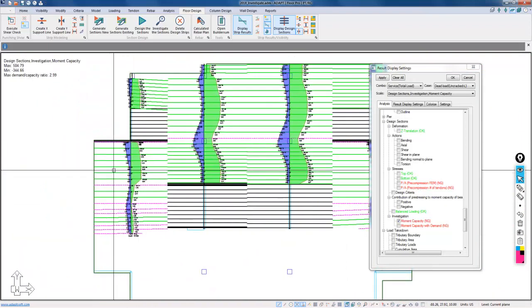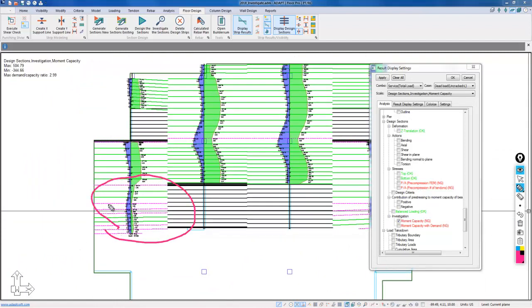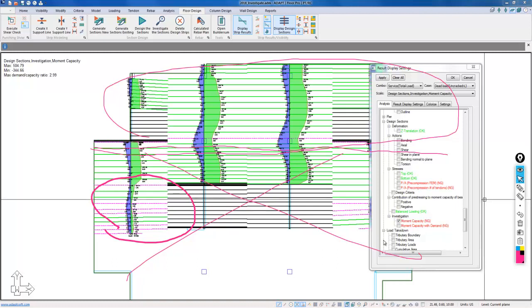Notice also that if you have a design cut, for example, we have actual design cuts back here, the program will check those design cuts also. So we may want to avoid what's happening back here, but if we put a support line back there, we're going to get results. So in our case, we're really only concerned about what's happening up here, so we just essentially ignore that, or we don't extend the support line back there, and we would actually put a splitter here, and all of this would basically go away if we're doing a partial evaluation of a partial slab in this sense.